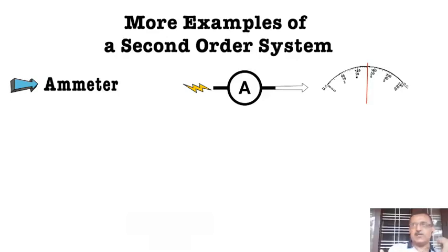And if you send 1 ampere current and if it oscillates, that also is not good. So we want the ammeter to be damped properly. Even critically damped is not good damping. So it is found that a damping ratio of 0.7 is good, and it depends on the application what you are doing it for. Okay. So I hope you understood the ammeter example.